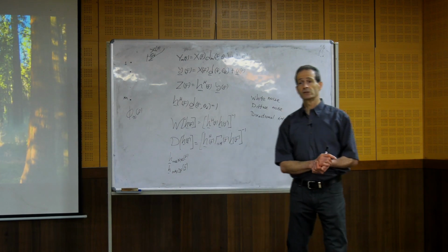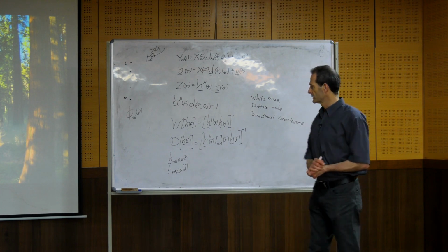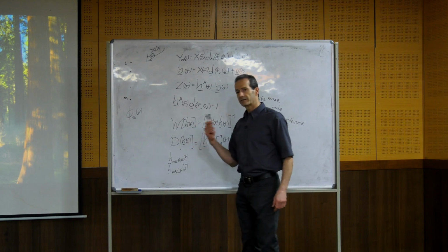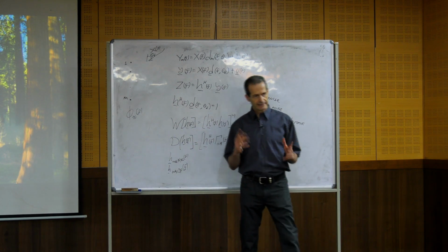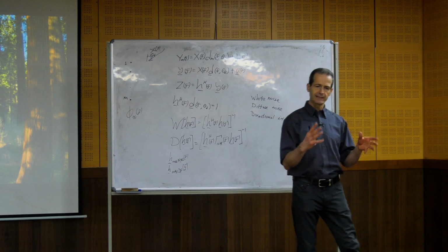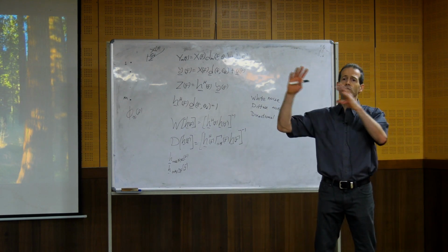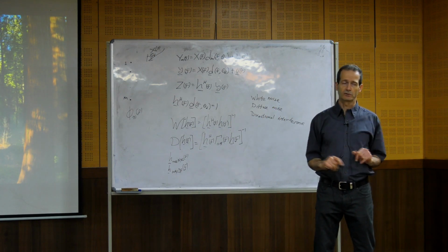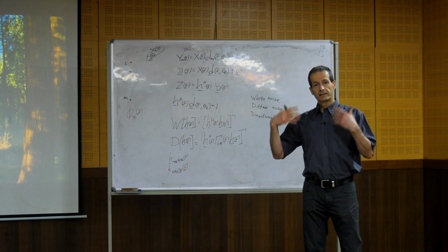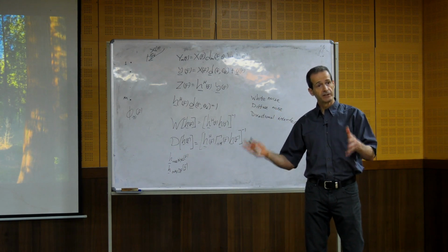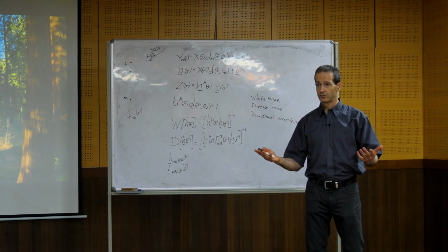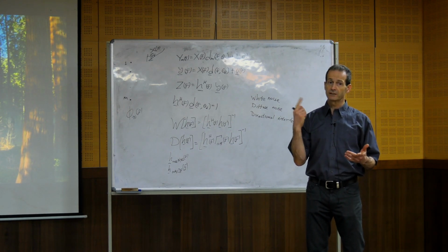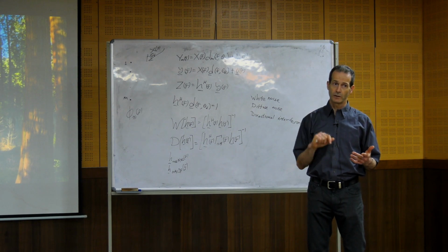And this is a nice result, because it means that if we designed a beamformer with the objective to get maximum white noise gain, which means that we designed the beamformer such that it will be used in an environment with only thermal noise, no diffuse noise, then if in the actual environment there is some amount of diffuse noise, it will not be amplified. The directivity factor is larger than 1.